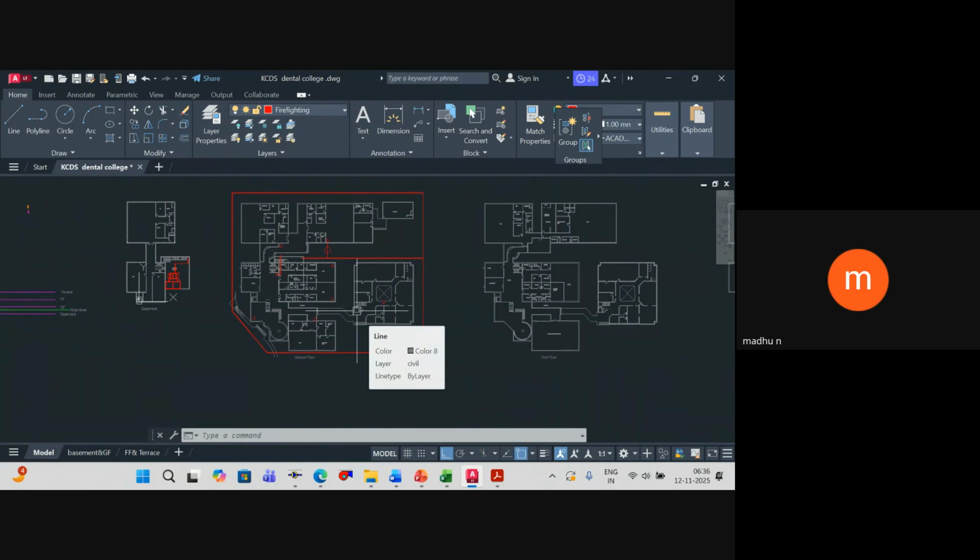But now, since you want to add one more zone, how do you add that zone? As of now, we have made for 3 zones, right? One more zone, how do you manage that? We'll add one more alarm valve, that's it, right? And we have to add one more riser pipe. Okay. That's it. What's a big deal with that?